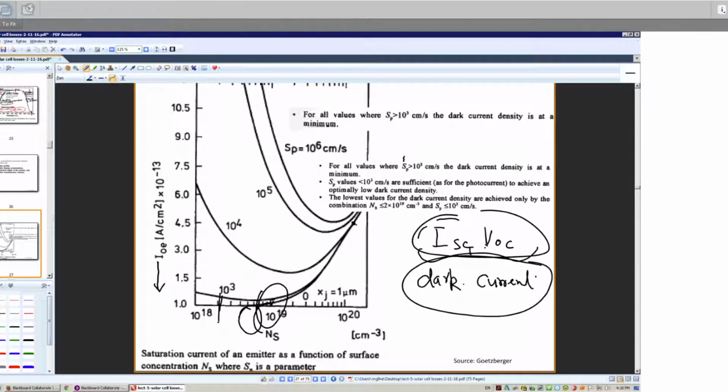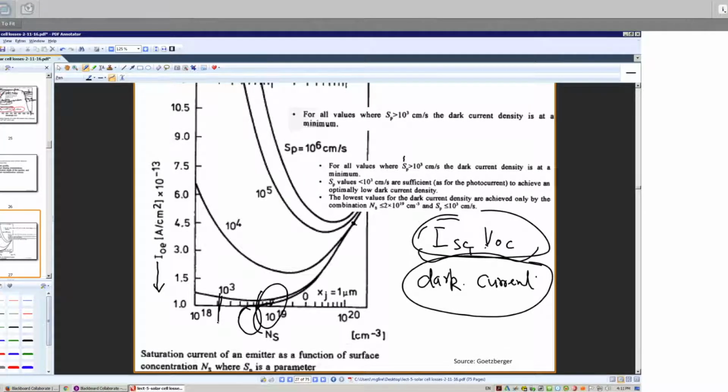Once the surface recombination is affected, what else? If your doping is low, that's right, because it will be more resistive. It gives you lower conductivity or higher resistance. So if you lower the doping too low, then your resistivity will be higher and conductivity will be lower. That will affect your fill factor and that will affect your efficiency. So again, there are always trade-offs. You have to be in a region to compromise one effect versus the other effect.